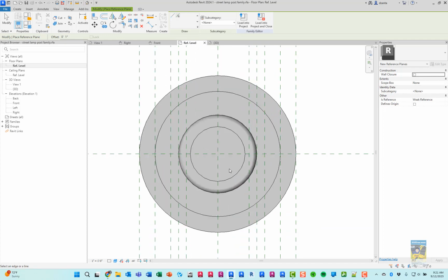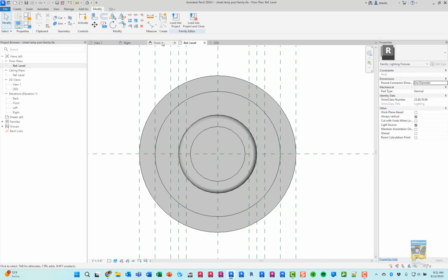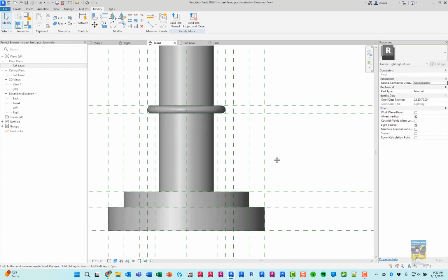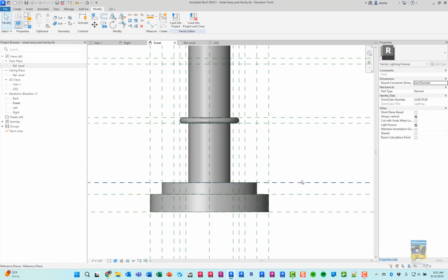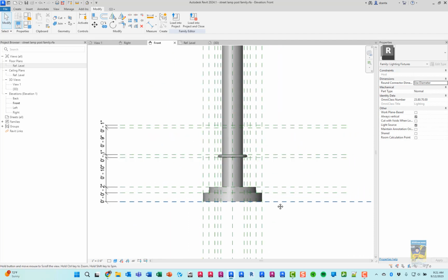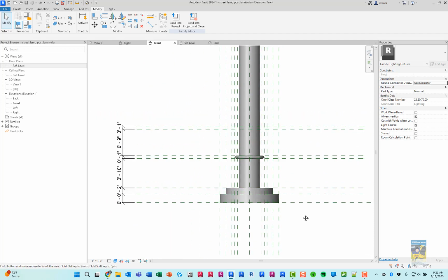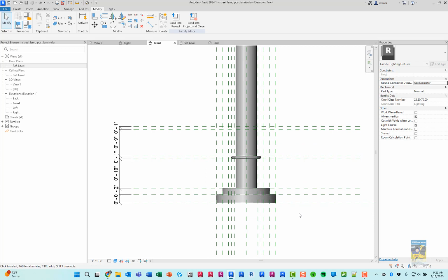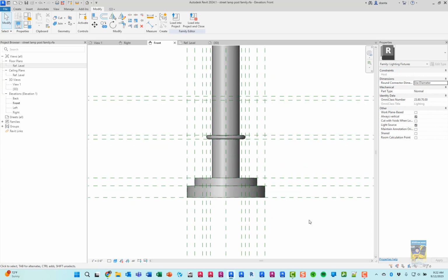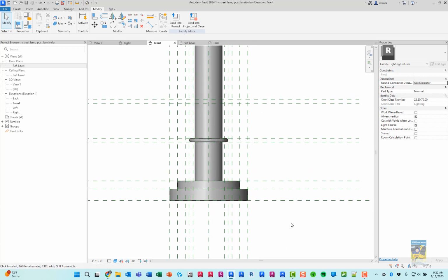So I'm going to do a blend that goes at the base plate, using this here as my visual indicator for the diameter, down to another cylinder at the top, using this as my indicator. Now, before I do that, we have to make sure that we know what planes we're going to be using to go from bottom to top. If you notice, I created all these reference planes, but I didn't give them any names just because I was working quickly. You really should name them for the sake of use down the road, because you might need to refer back to them again when you're doing different Boolean operations.